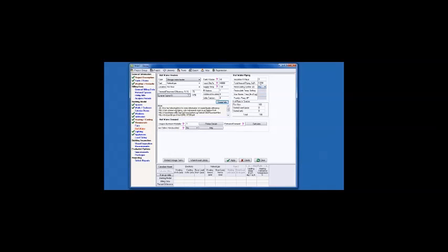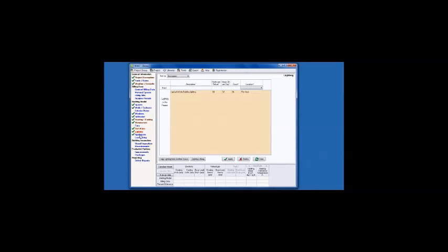Again, defaults of pipe insulation and where it's located. Probably in this case, most of it's down in the crawl space if the water heater is located inside, and probably has some pipe wrap on it. There's some feedback to tell you gallons of water per day per person. 17 sounds pretty low to me. I might double that. Now I'm up near 30 gallons per day per person. That sounds pretty reasonable, but obviously that's gauged upon you knowing the homeowners and talking to them.